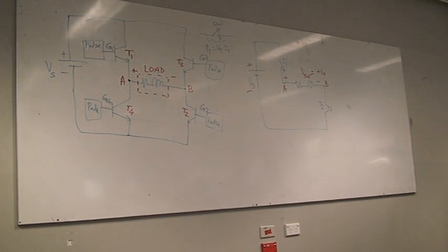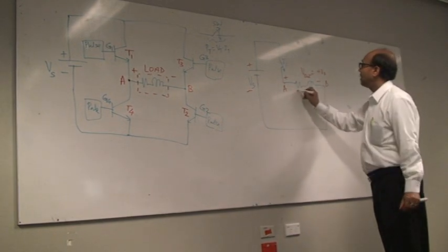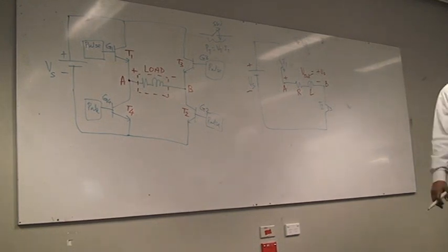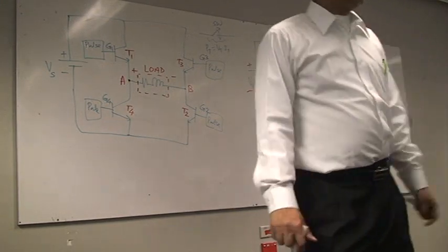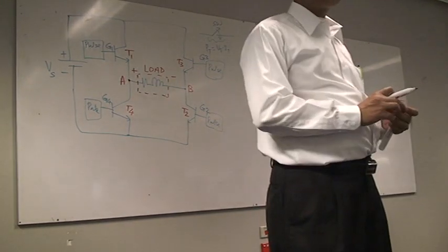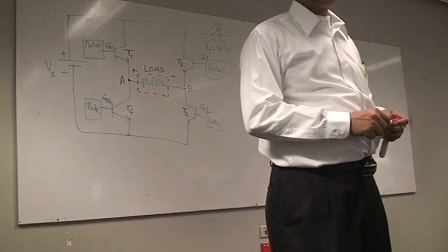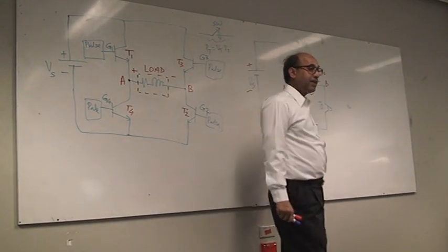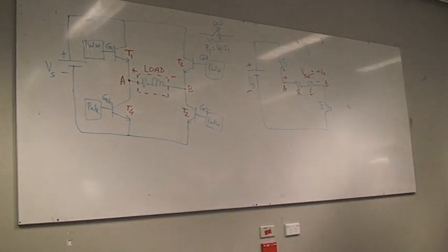Now you switch it off. Now when you go to switch it off, you are in trouble. Why are you in trouble? Because you have got an inductor in series. An inductor is like a lazy fellow. It's not active like Subhas. He will tell, no man, I don't allow the current to change very quickly. You understand? So you're trying to switch off these two transistors, but the inductor is telling, no, I won't allow this current to change.